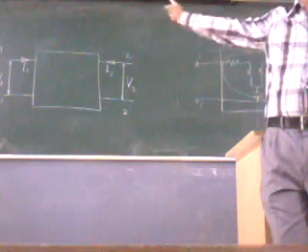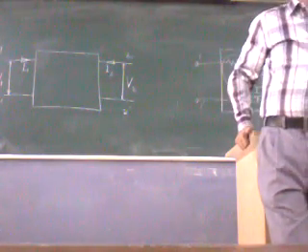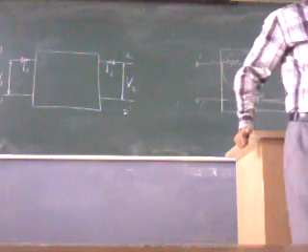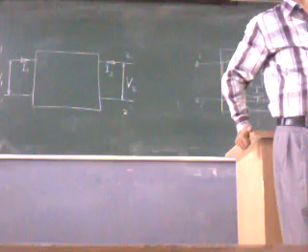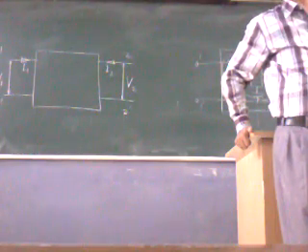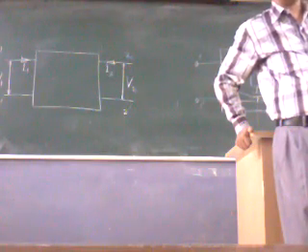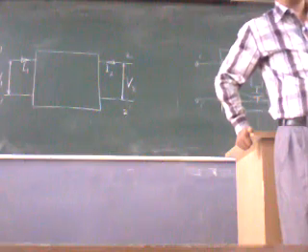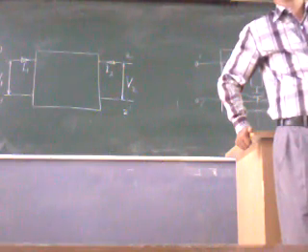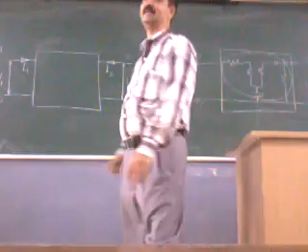I may have a very complex circuit inside. But whatever may be the size of the circuit, Thevenin has provided us a way with which I can look at only 2 values for the circuit. Are you getting me? What Thevenin has provided me? The magic way. However complex the circuit may be, I look at it from 2 points and I only look with 2 parameters. One is VTH and one is RTH. So for a 1-port network, I can entirely describe it.